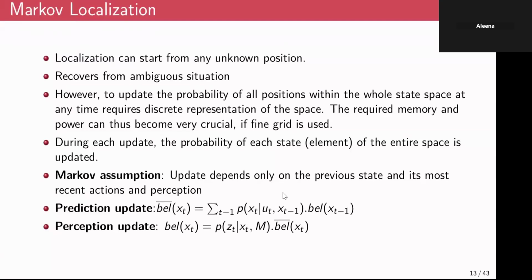If you can recall from the lectures, the professor showed a very clear problem on how to implement this Markov localization. It's actually based on probabilities. You first create a grid of positions. You discretize your map into discrete grids, and at the beginning you assign equal probabilities to all these grid points. The robot could be anywhere within that grid with equal probability.